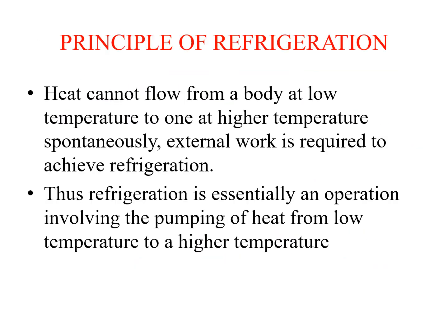Refrigeration implies production of low temperature by continuously absorbing heat at a lower level and rejecting it at a higher level. The principle of refrigeration is that heat cannot flow from low temperature to high temperature spontaneously. So external work is required to flow heat from low temperature to high temperature. This external work is required for achieving refrigeration also. Thus refrigeration is essentially an operation involving the pumping of heat from low temperature to high temperature.